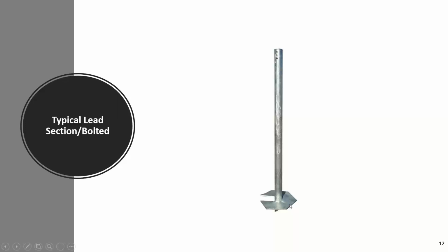So we go to the lab and we test it. We call it a flexural test also because we're going to bend this helix, and we're really testing the strength of that helix. We find out that if we put this structural ribbing over here, there are like 5 of them, they increase the helix capacity from like 30,000 to almost 50,000 allowable. This is allowable. And if you go to our ICC-ES report 1559, you will see that the allowable helix capacity for the 2 7/8-inch outside diameter shaft is like 50,000 allowable. It's almost 15,000 to 20,000 pounds more than the others without this structural ribbing.